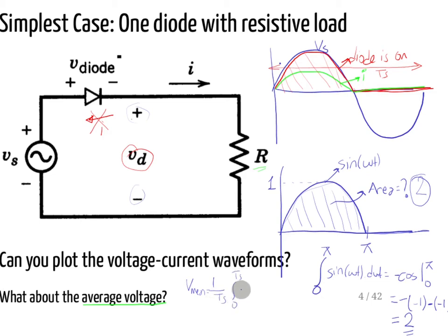So basically the integral of v dt, okay, so that is equal to, the time length will be 1 over 2π, and that area is 2 here and 0 on the other side, so it is basically 1 over π. Of course this is for a waveform having a magnitude of 1, and here this is our peak value.